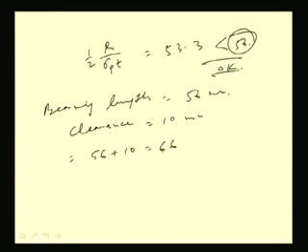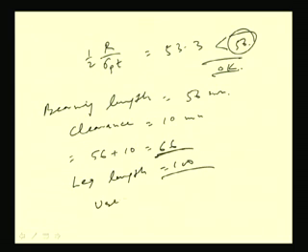So let us provide a leg length of 100, because required is 66. So we can use the seat angle of say ISA 100 into 75 into 10. Let us provide the seat angle as this. I am not going into the details of the seat angle; we will see the stiffener angle.